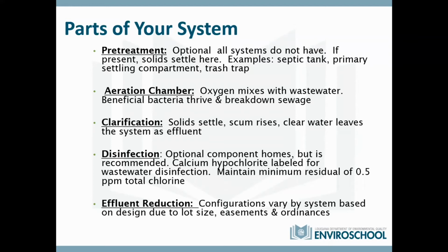Then we'll have some sort of clarification. That's that clarifier chamber. After the water slows back down, the solids settle back down and return back to the aeration chamber. If there's any scum left over, it'll rise and will not be able to go out through the pipe. Hopefully there won't be any scum on that side of it. And then the clear water leaves the system as effluent.